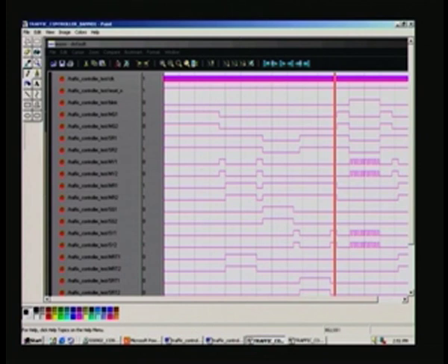Here first, before zooming this output, I will just explain what these signals are. First one is clock, and it is too high a frequency, you can't see the clock because it is in megahertz and we are in the seconds region here, right, 45 seconds etc. So, naturally you can't see the clock, and there is also a power on reset here, and that is of duration 20 nanosecond. So, that gets merged here, you can't see that, and these are all the usual signals that we have been used to in several designs before.